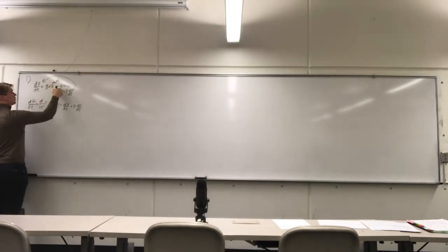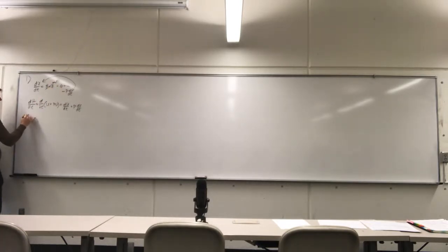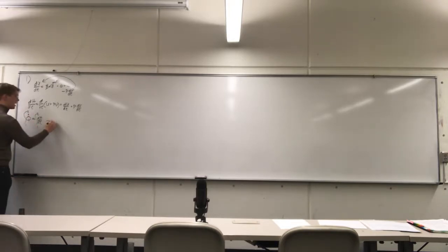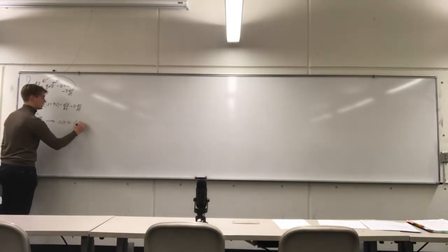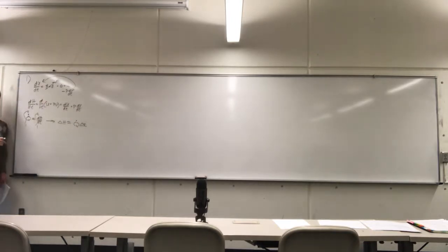Closed system, this goes to 0. So then ultimately what we're left with is Q dot, the rate of heat transfer, is equal to the change in enthalpy, dH/dt. So now we integrate both of these from state 1 to state 2. And then what we get is that delta H is equal to Q dot delta t, where if we integrate this expression, what we're looking at is the integral of Q dot dt.